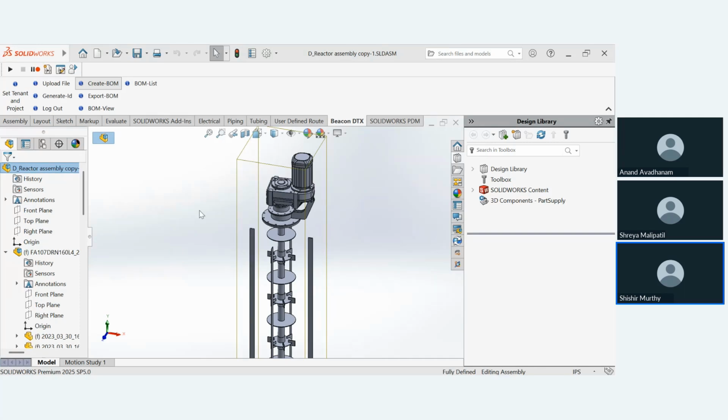Now, why we have done this is because you might have certain bought out, but by the design, you would have created it as a sub-assembly or a component, which is set of item, which is set of designs in it. But you don't need that for the competition, so you can just dissolve it and have it just the top level here using the delete option, and then you associate the required item code to the CAD part of it, and based on what is in item master.